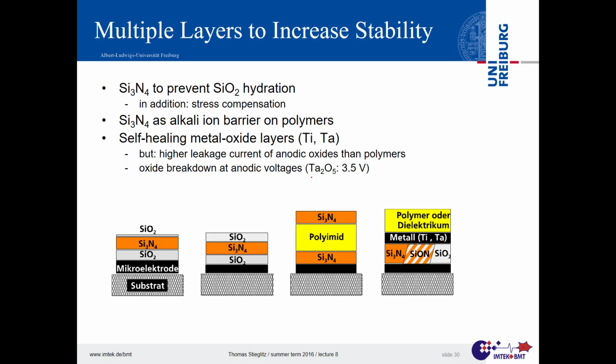For those of you who have heard about the Fermi level in one of the more serious lectures, this is what happens here. So by putting silicon oxide and silicon nitride together, for example, the activation energy gets larger to destroy that material, since the Fermi levels get distorted there at the interfaces. And this is good, but we always have to think twice if this is then really improving the whole material, but these combinations are a good step.